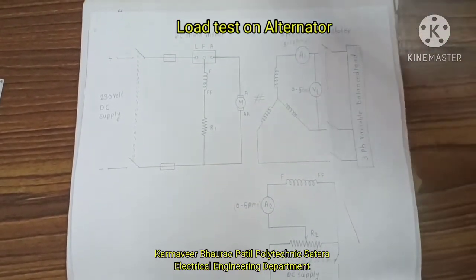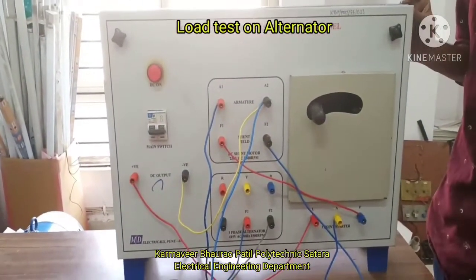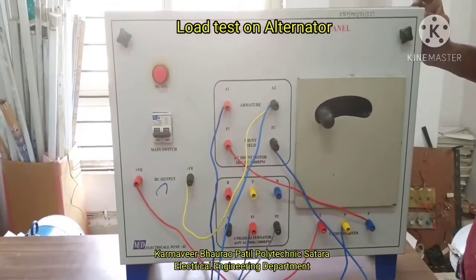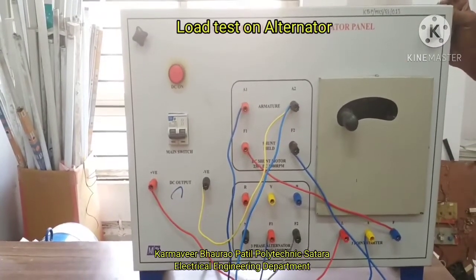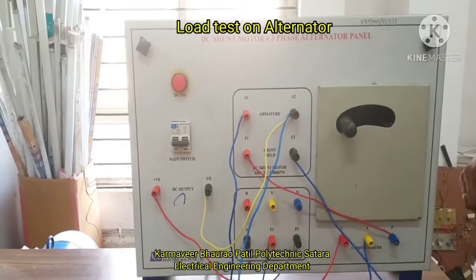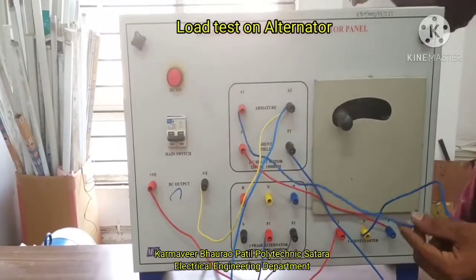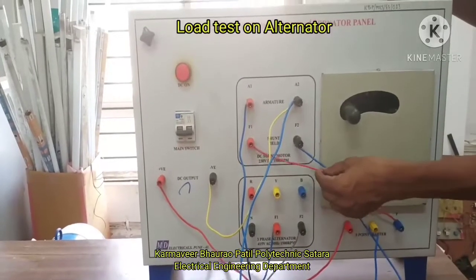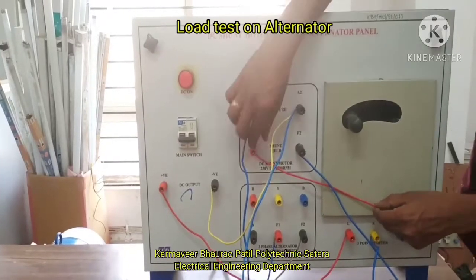Starting from the supply terminal, supply positive will go to the L terminal of the 3-point starter. Then the A point of the 3-point starter will go to A1. Then the F point will be connected to F1.